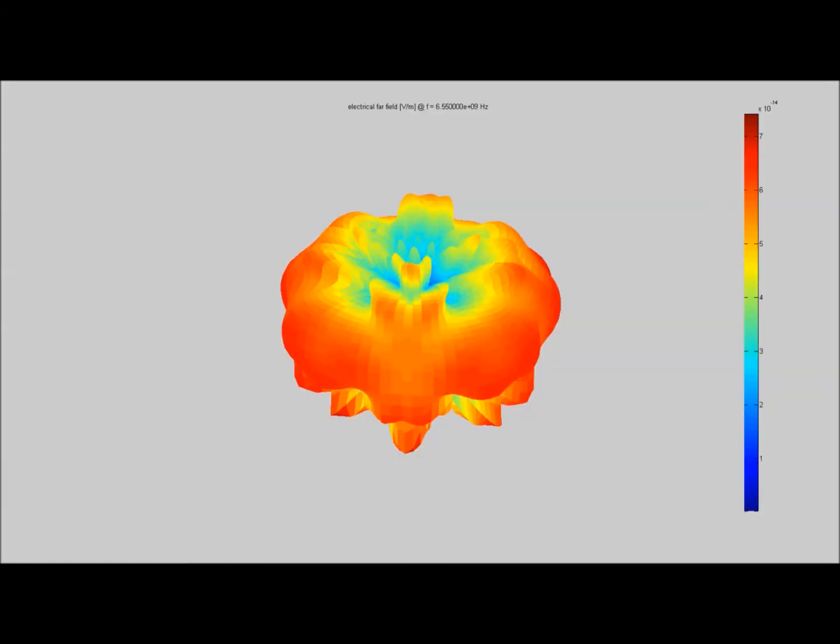The far field graph of our antenna looks much better in 3 dimensions. We can see that it almost encompasses the hemispherical shape that we're expecting. We have no 3D field in the paper to compare our 3D far field with. However, we know that dielectric resonator antennas are expected to emit a hemispherical rounded field.